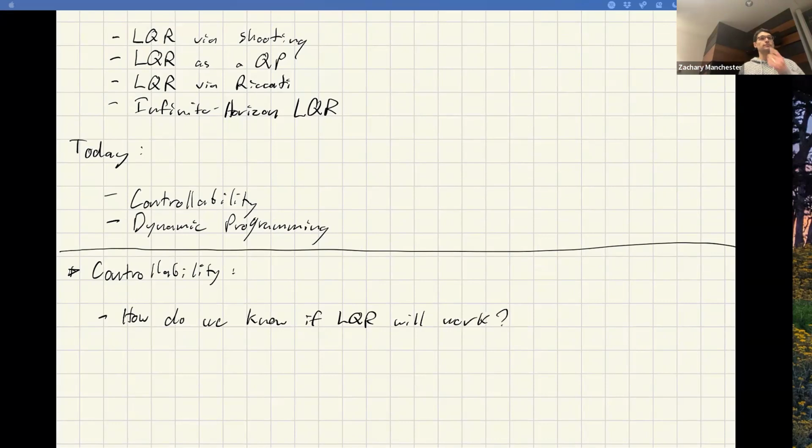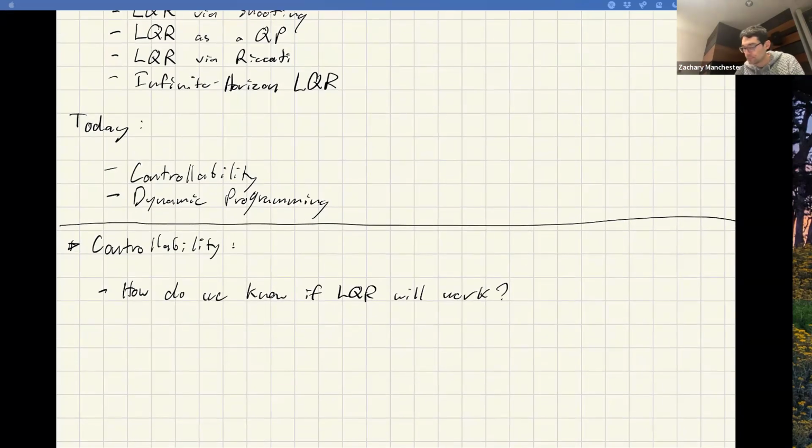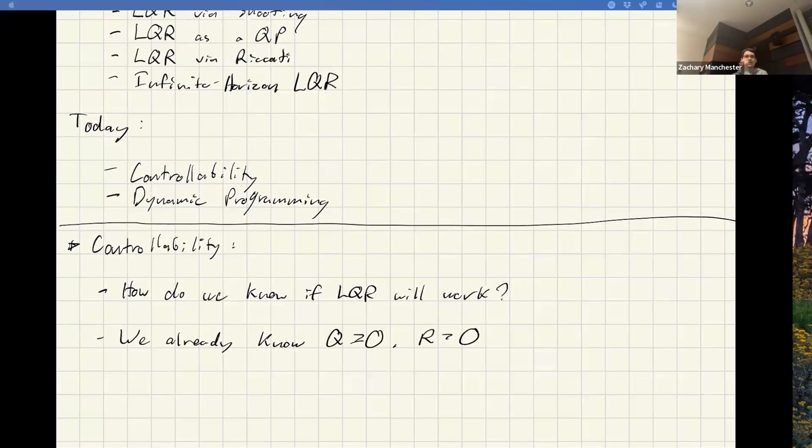So this pertains only to the system. With respect to the system dynamics, you can technically take the state of the system to any state that you want. That's another way of thinking about it. It turns out for linear systems, because superposition holds, this is equivalent to always being able to drive the system to the origin, right? Because of linear superposition, I can just subtract a constant and make anything the origin. So all I have to worry about is the origin.